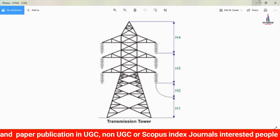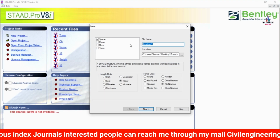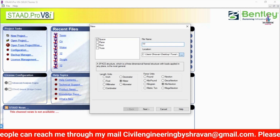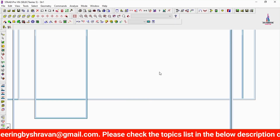For that, firstly I am selecting the Staad Pro V8 software here. Click on the new project option, select the space option. I am changing the name to transmission tower. Select your folder. I am selecting the folder as tower. Select the length units as meter and the force units as kilonewton. Click on the next option, then click on the finish option.